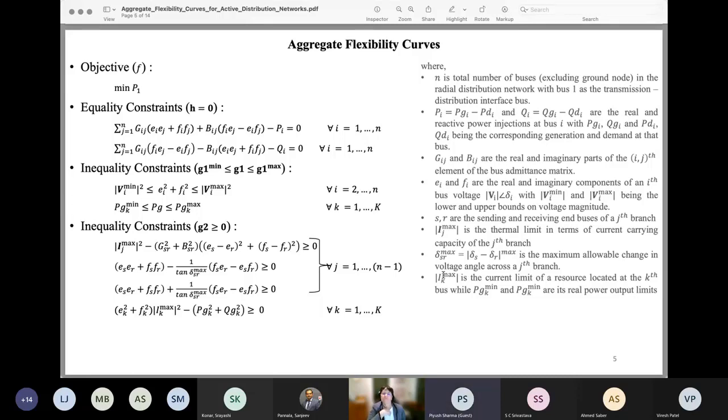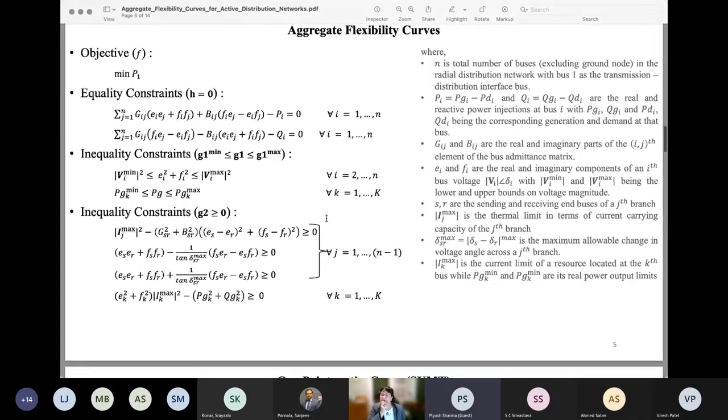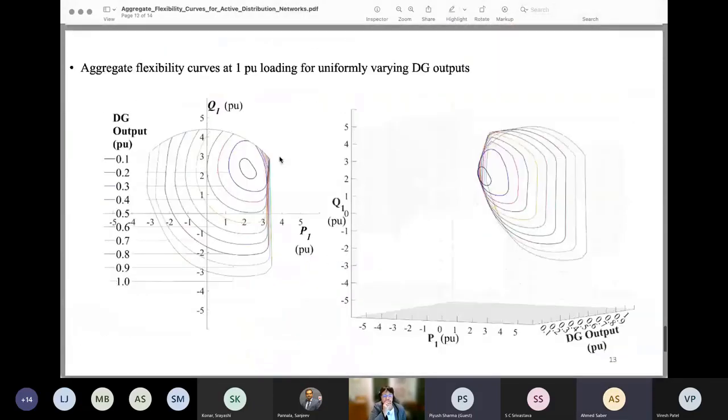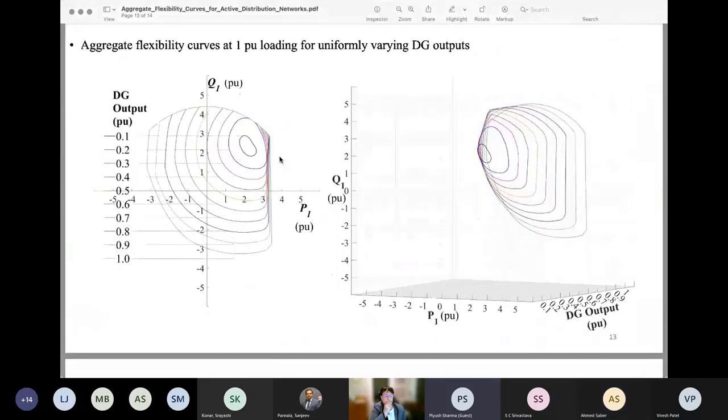As of now, this algorithm has not been modeled with respect to time. So there is no time variable; we do not consider that. What we can do is this: this whole curve gives the worst-case possible situations that can happen when the loading level goes down to 0.6 or up to 1.4. In one particular optimization exercise, I cannot take care of the time aspect, the ramp and other dynamics. That is absolutely true as of now. But I can share these curves in advance so the operators can decide, depending on the loading, whether the point will be static secure or not.